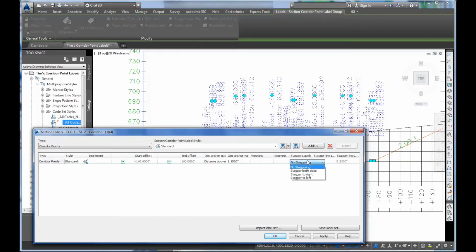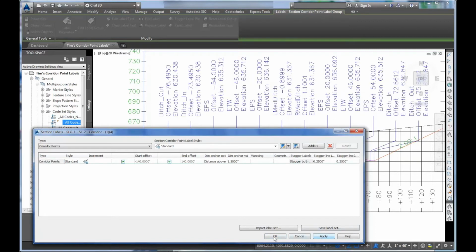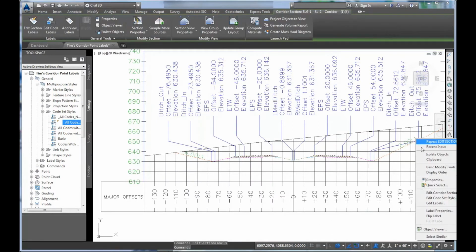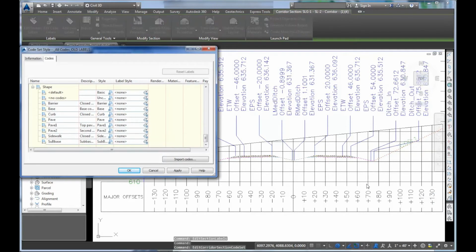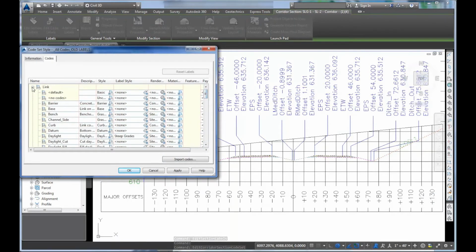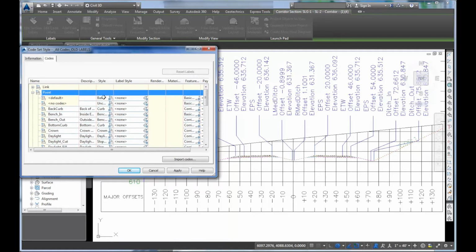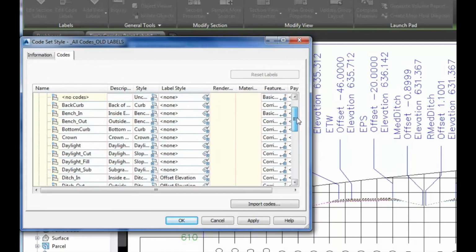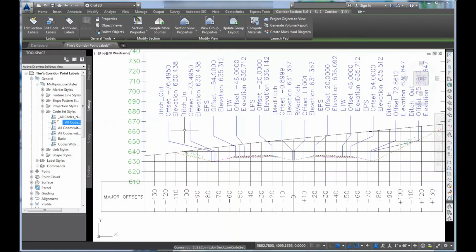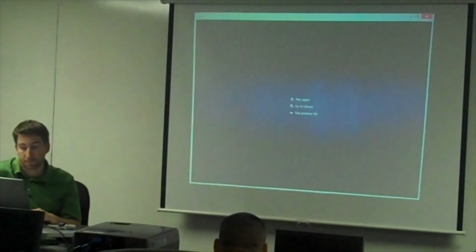It's going to take overlapping labels and straighten them out, so you're labeling the correct point, and it's spreading them automatically for you, which would take a lot of manual manipulation otherwise. And then here's where you tell it which particular points you want to label and how you want those to be labeled. So it's picking up meaningful points off of that typical cross-section in the scene.